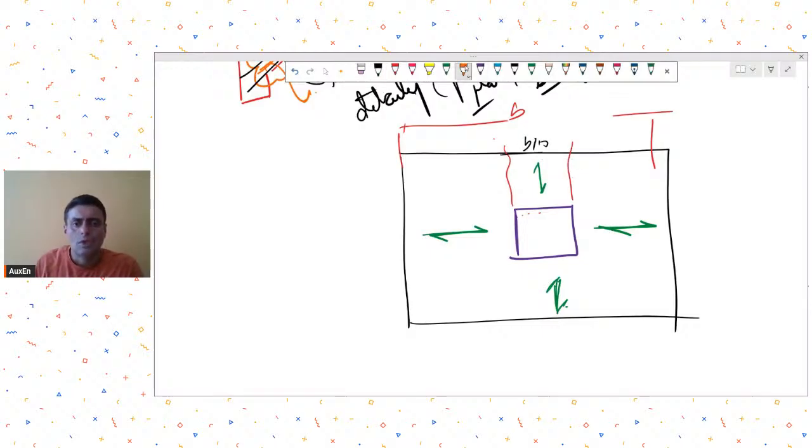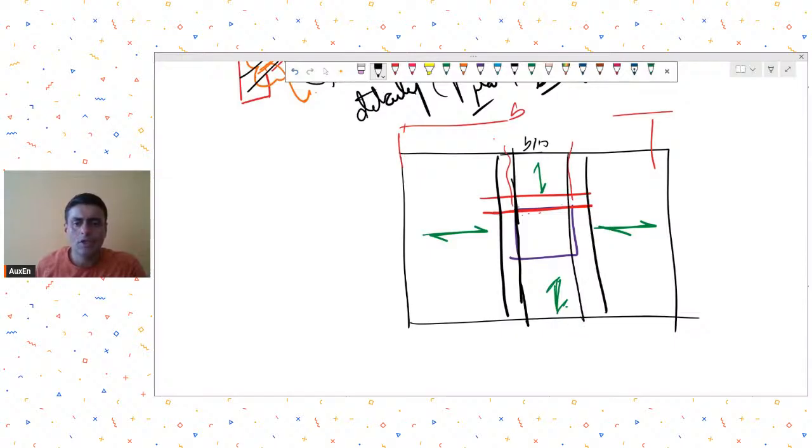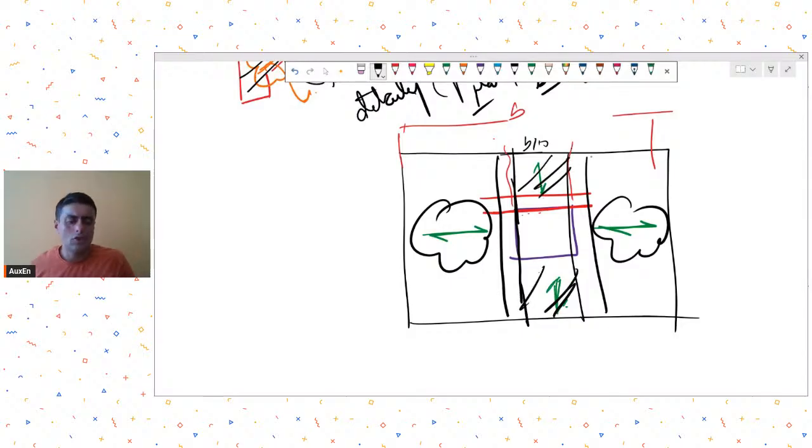Okay. So you need to ensure continuity of load path. So the best way to do that is to have some beam elements added over here. These beam elements will be sort of concealed beam elements within the slab thickness. See, if the cutout is large, then the first suggestion would be to have an actual beam. So this actual beam will help you to support this slab, and support these slabs also. Okay. So for large openings which are going to be loaded, this is the best way to do it.